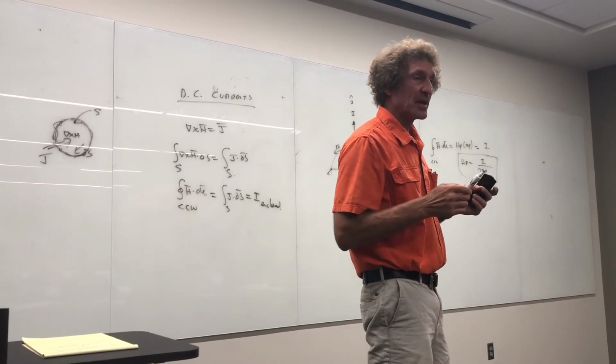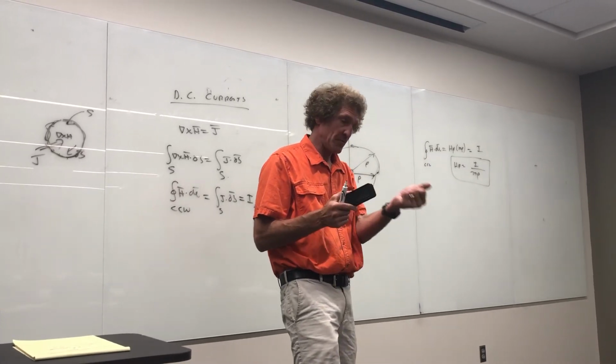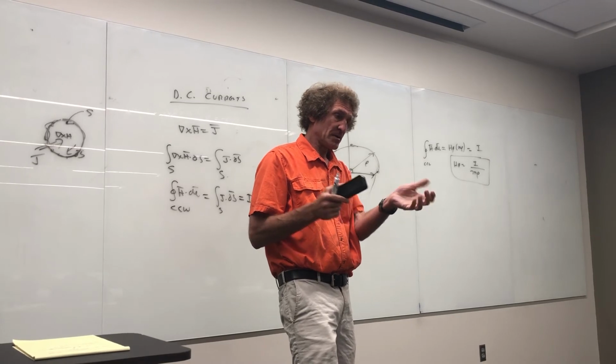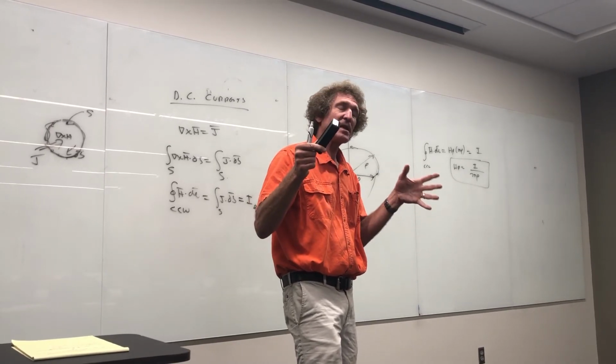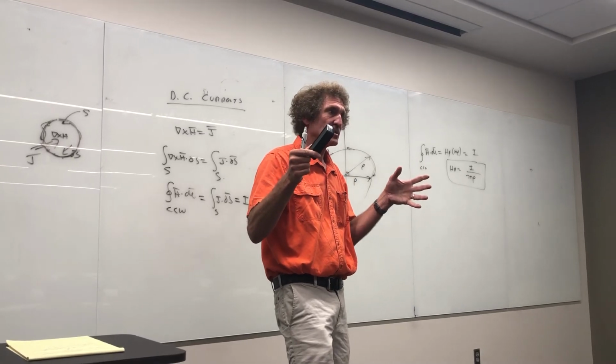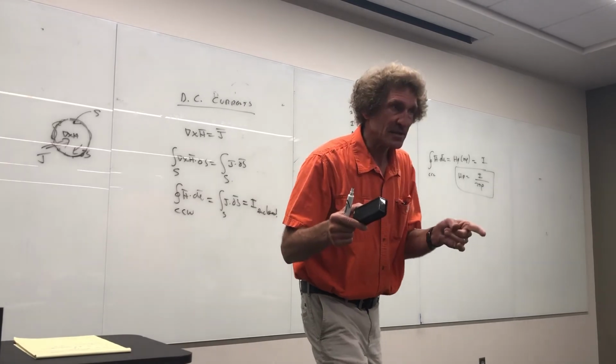If you pick a point and take a look at the differential H field in your mind from each one of those current elements, everything cancels. The funny thing about a spherically symmetric current distribution is that if you put current into the inner electrode, you get no H field. I mean, you'll get a little bit of an H field because there are asymmetries. Nothing is perfectly symmetric, but you virtually get no H field, which means no inductance.